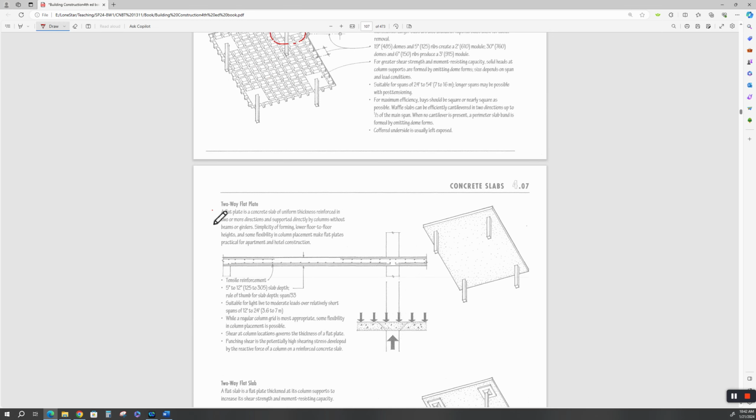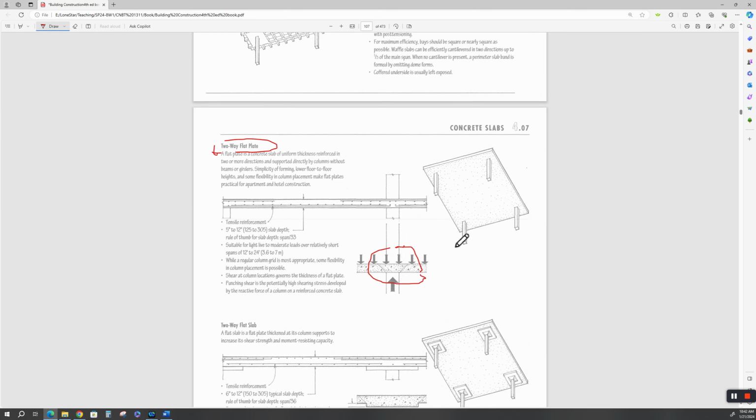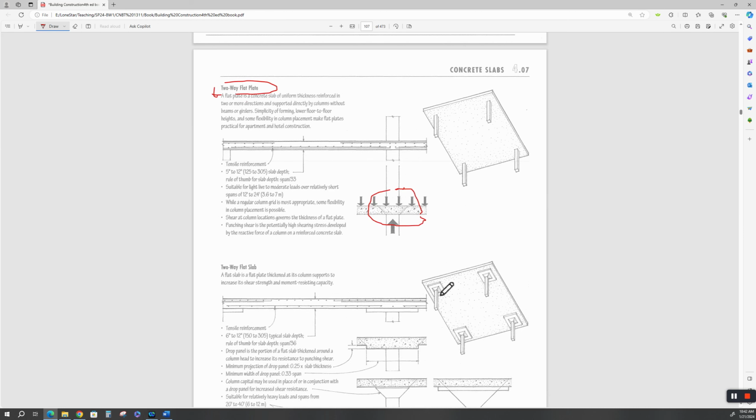All right, two-way flat plate is nothing but a solid piece of concrete over columns. I'm not a real good advocate for this because this really makes me not sleep at night. And they look cool because the bottom slab is clean, right? But, and again, there's some rules of slab over here, but you really got to watch your punch and shear. That's a structural engineering thing.